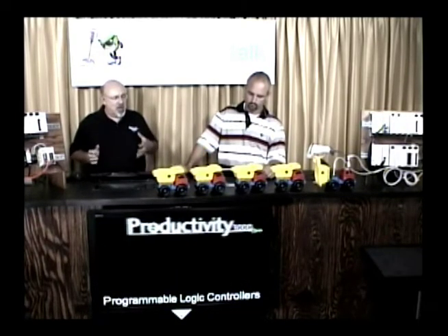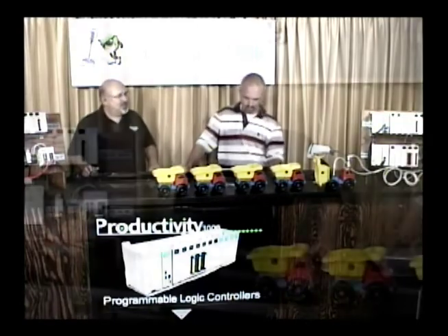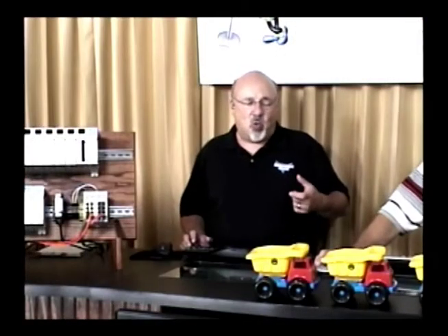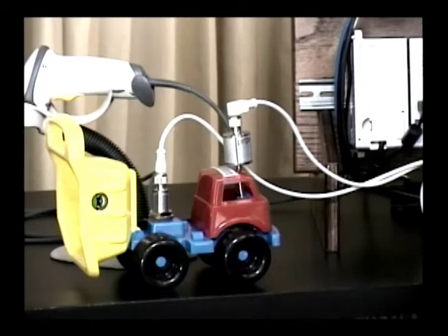So during the assembly process, we'll get this all together, and then with a proximity sensor that senses distance, we're actually going to measure what we'll call the end play of that axle and the bearings. At the same time, we're also going to check the temperature of that axle, because metal, of course, contracts and expands based on temperature. From those numbers, we can calculate how much preload we need to adjust on those bearings later in the assembly process.